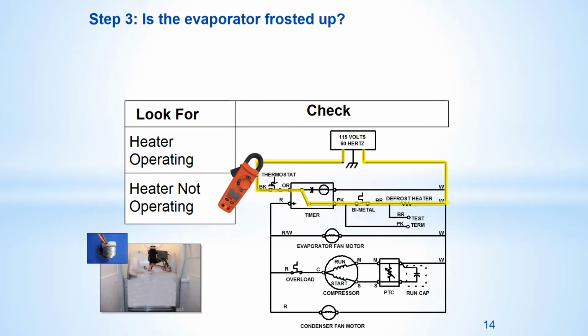You should allow the defrost cycle to continue while monitoring the current. You could do this while you disassemble the evaporator cover and begin defrosting the evaporator manually along with the defrost heater helping, but don't put any direct heat onto the bimetal. This way you can see if the bimetal is cycling prematurely. And just because a bimetal looks good doesn't mean that it is. If the defrost current stops with the bimetal still encased in frost, and it's still in a defrost cycle, this indicates a weak bimetal, and you can verify that it is the bimetal with your voltmeter.